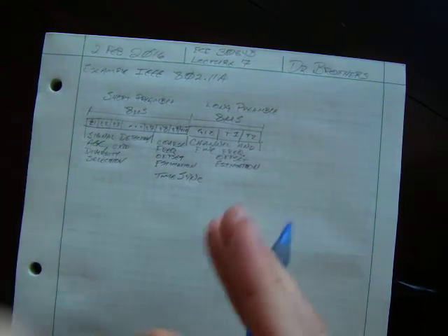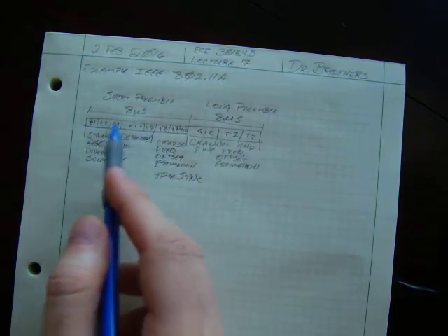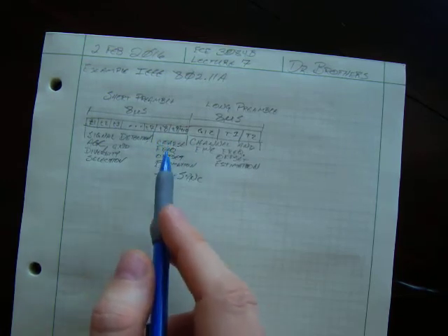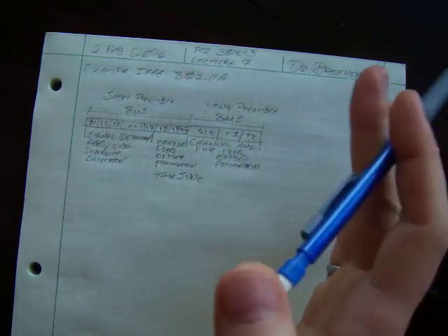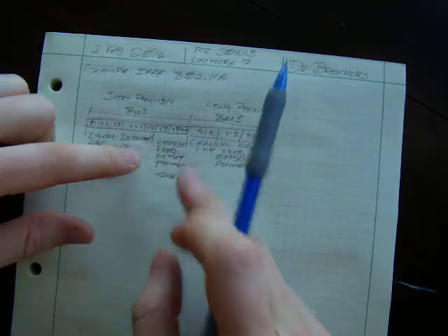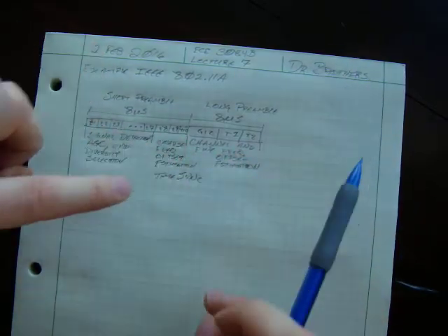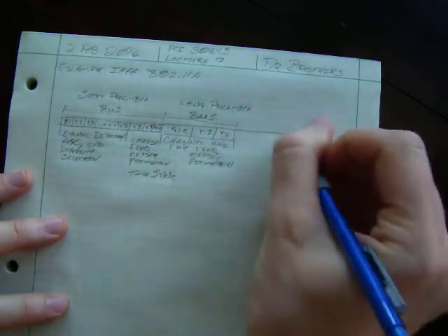Each bandwidth of data is broken up into a number of channels. So this first part just lets the receiver know that a data packet is coming. This one lets them lock onto the signal. This one tells them which channel. So it keeps getting to a finer and finer level of granularity. This first one is just looking to detect the signal. This one is a coarse frequency estimation. This one is the fine frequency and the channel. So it just narrows it down the more of the preamble that's processed. The last thing that comes through is the data.